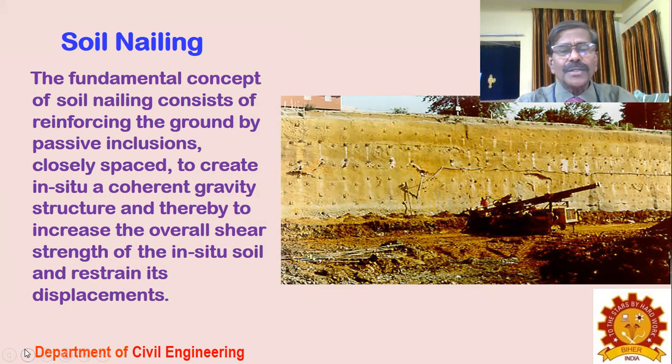It is predominantly used for soil stabilization in the case of roadways or highways where you need the space for a service corridor also. We may not have the embankment on either end of the elevated corridors, so you have to have the soil nailing.